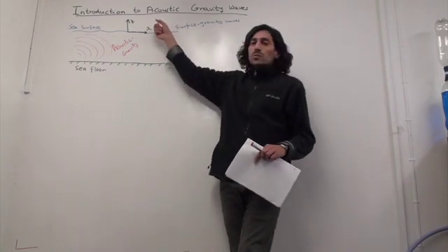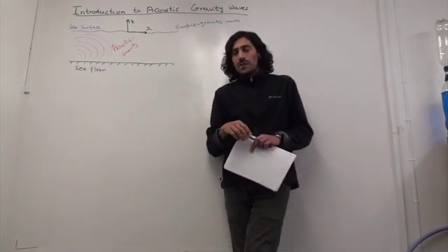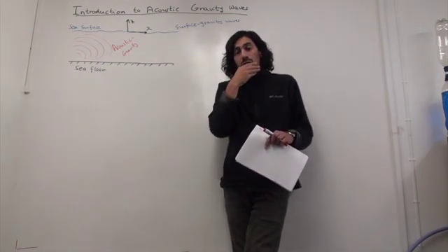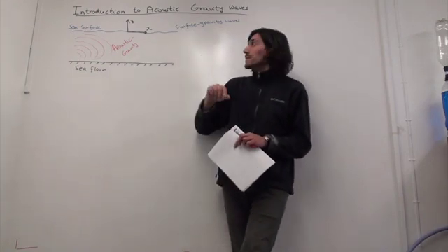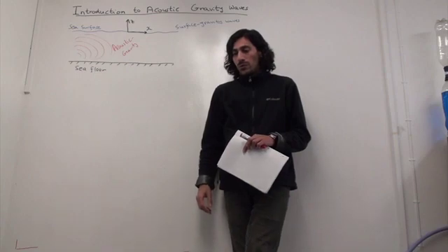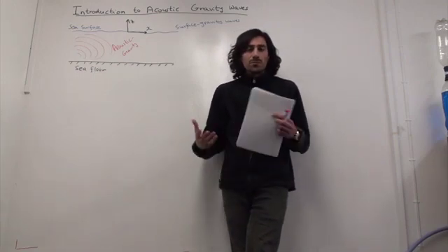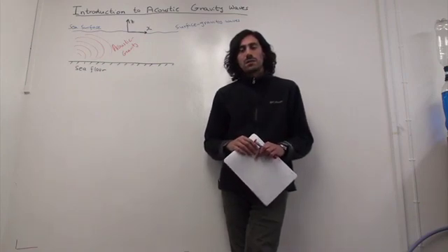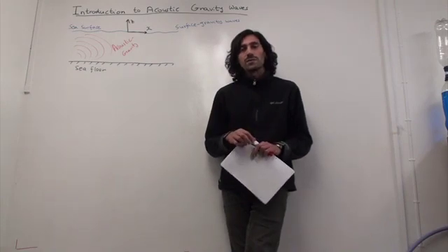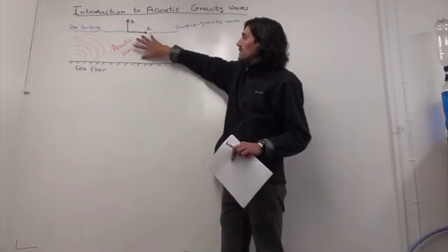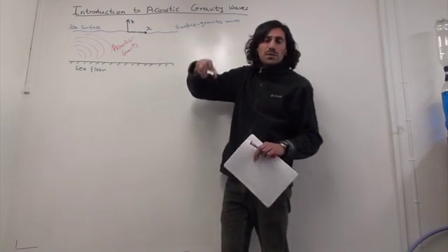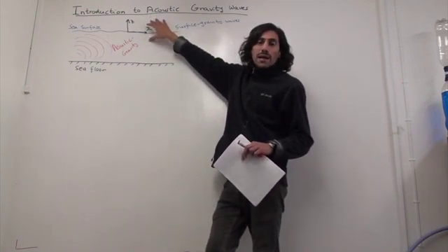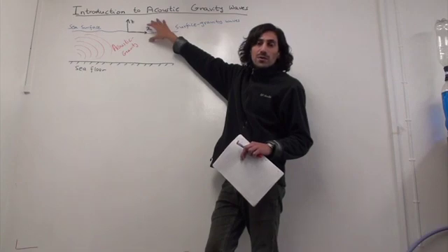So when you're discussing gravity waves, like the water waves, let's say the short regular water waves that you see in the ocean, when you go surfing, you don't want to see a tsunami. So when you're talking about these waves, the compressibility of the water practically does not add anything when you're solving the equations. It's minor. It's negligible for most practical reasons. So you don't really need this acoustic term, or the compressibility of the water, in order to describe the dynamics of the gravity waves, surface gravity waves.